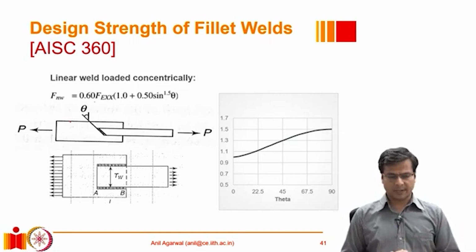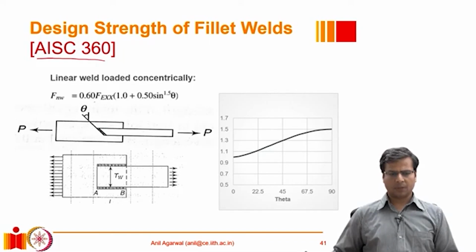What does the international practice involve? Internationally, as I had mentioned before, for example, if we take the example of America, in the US, the prevalent design code for steel structures is AISC 360. And as we had seen this equation, the second part of this equation says that this material would have the strength of 0.6 times Fu. This FEXX actually represents the Fu, ultimate stress. So it already has a shear strength of 0.6 times Fu.